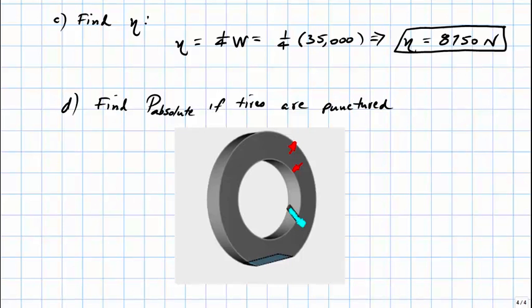The absolute pressure inside of the tire will push this column of air in an outward direction. However, since the other end of the stem is open to the atmosphere, the atmospheric pressure will actually try to push this column of air back into the tire. Since the absolute pressure in an inflated tire is greater than the atmospheric pressure, the absolute pressure will win this tug of war, and therefore this column of air will be expelled out of the tire.